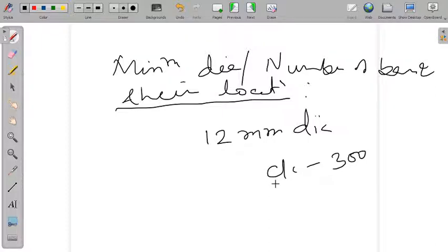Longitudinal bars are usually provided close to the periphery. When a large number of bars are needed, they may be bundled, or alternatively grouped. So this is how the longitudinal bars are to be provided.